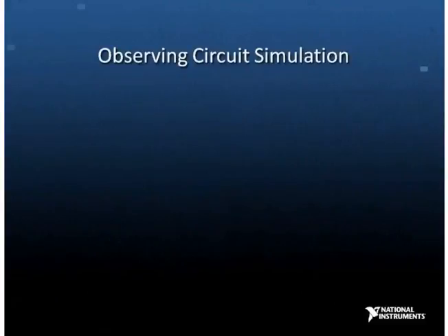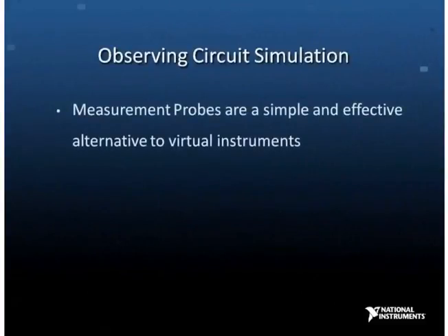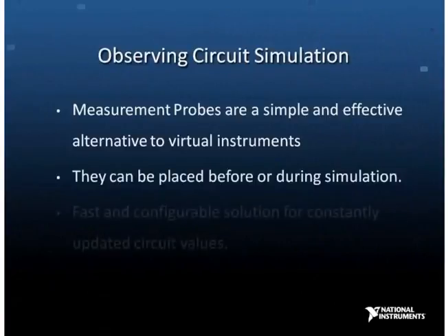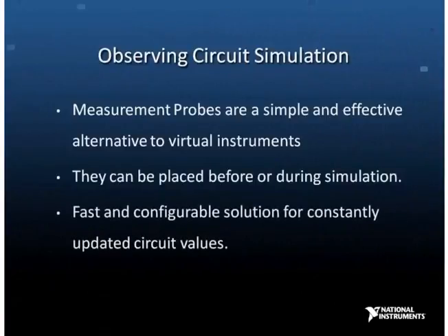A measurement probe is a simple and effective alternative to virtual instruments if you don't need circuit values and information with a graphical representation. One of the most important aspects is that they can be placed and used before and even during a simulation and give constantly updated values.